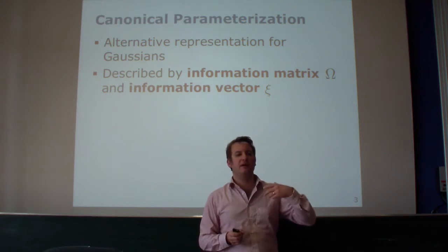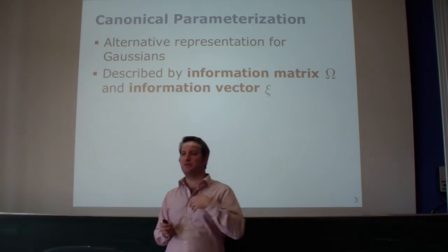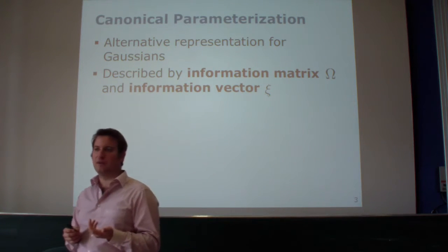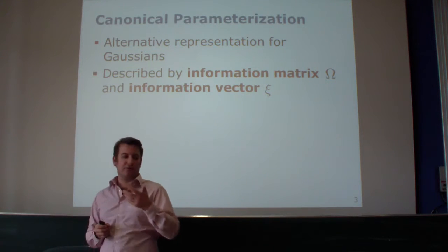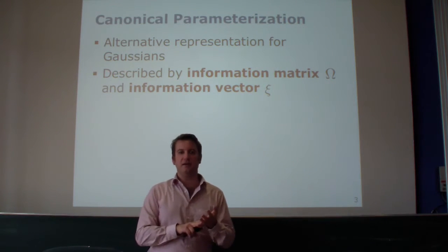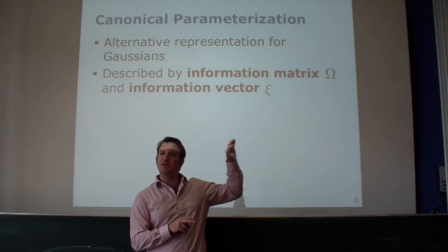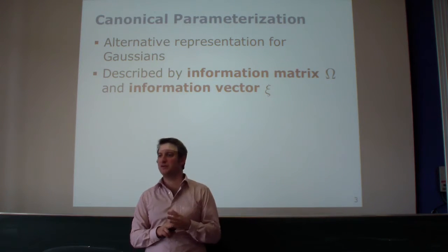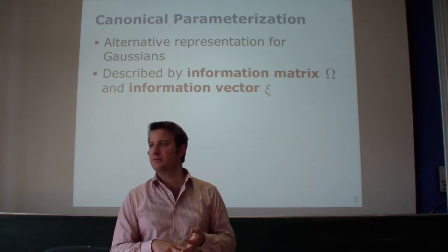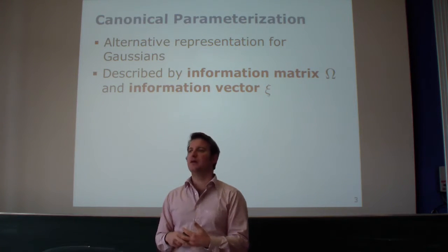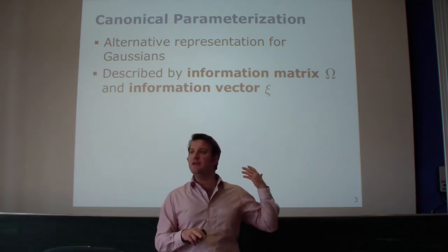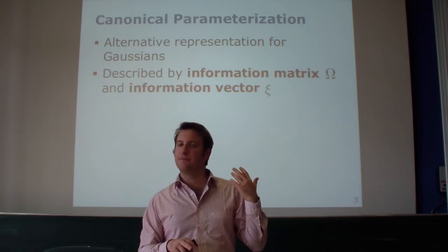The only thing is that the different steps, basically the update and the prediction step, change in terms of their complexity. It will turn out that the prediction step, which is easy in the Kalman filter, turns out to be difficult or complex in the information filter. And the measurement update, which is more complex in the extended Kalman filter, turns out to be easy in the information filter.